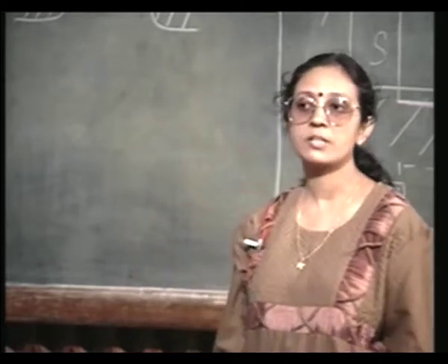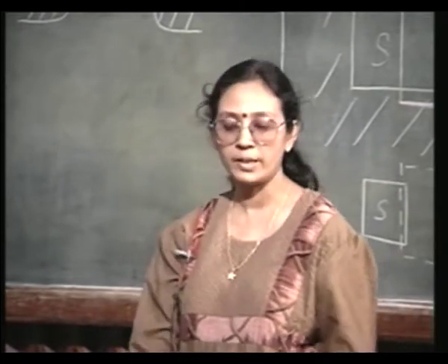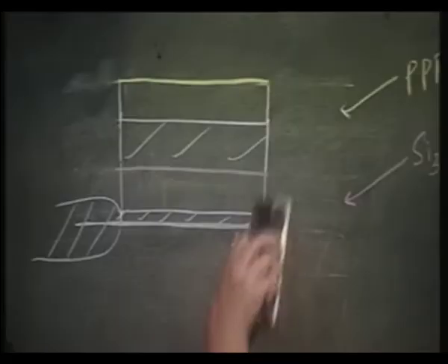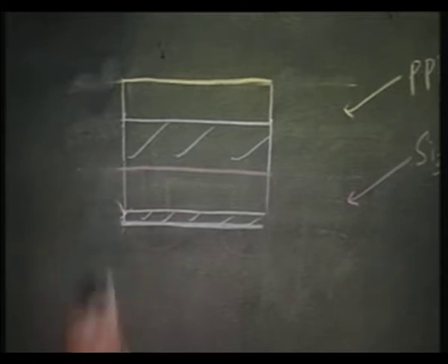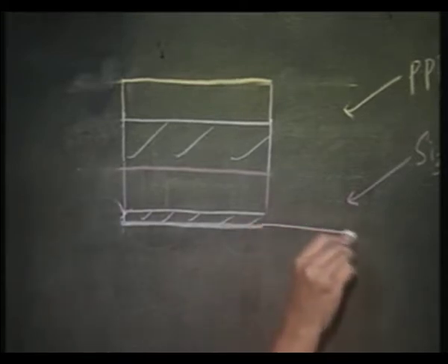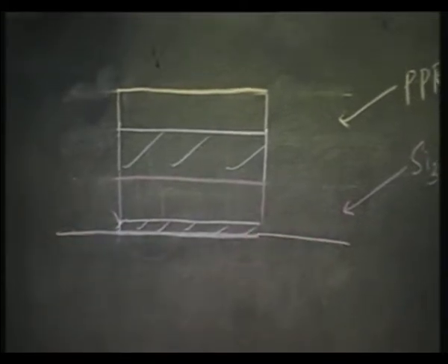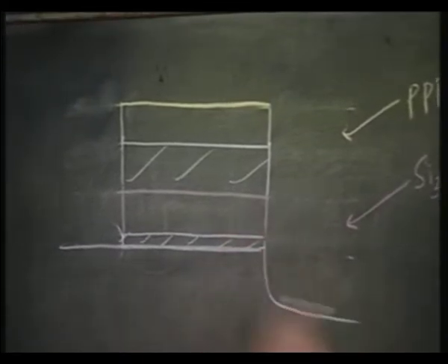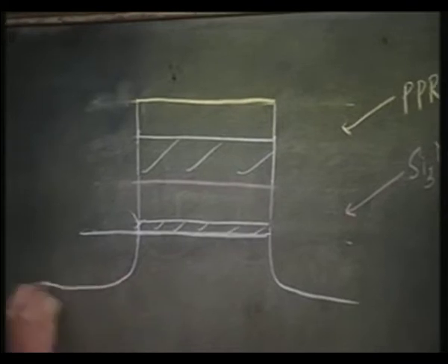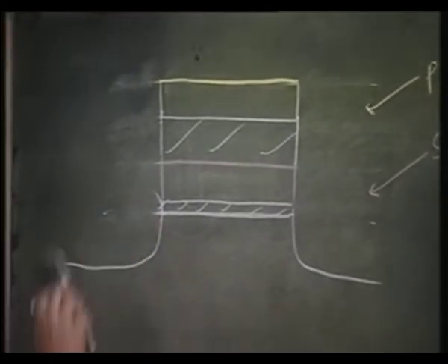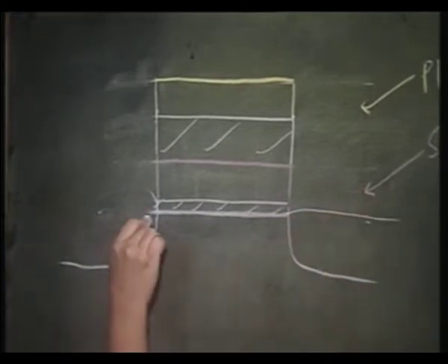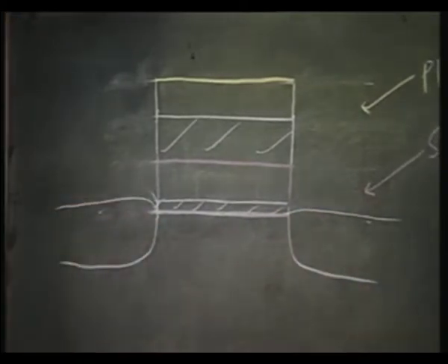If I want to make the surface more planar, I can first carry out an etching step and then follow it up with oxidation, so that the oxide comes exactly up to the surface.